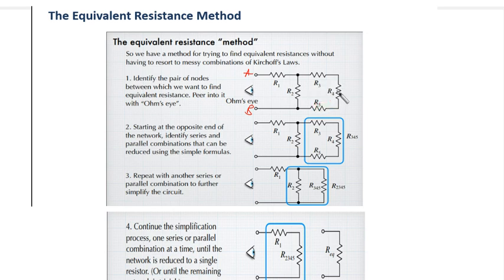If you look at it very carefully, whether the current is coming from this angle, if the current I enters here, it will go like this, it will go like this. So there's no other path that can divert the current from any of the resistors. So any current that enters either through this way or through this way, the same current is going to flow through them. So it means that these three resistors, since they are going to be carrying the same current, are in series. So we spot them like this.